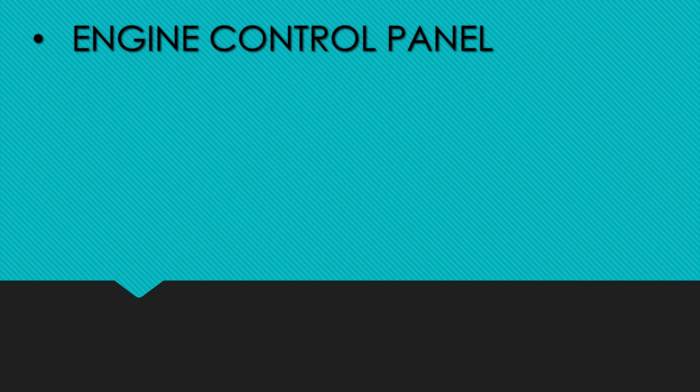Now let us discuss the second electrical component, which is the engine control panel. The engine control panel consists of control devices which regulate, rectify and adjust AC speed signal from the engine tacho generator. It also carries components for use in governor stabilization and speed circuits.